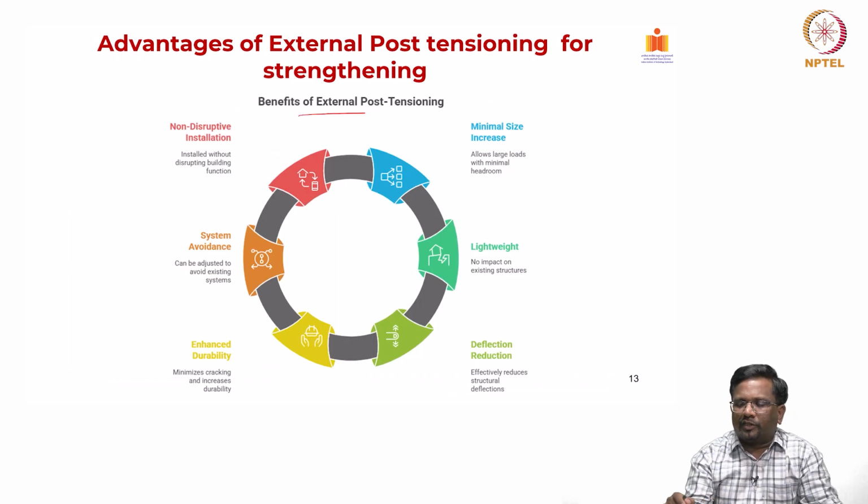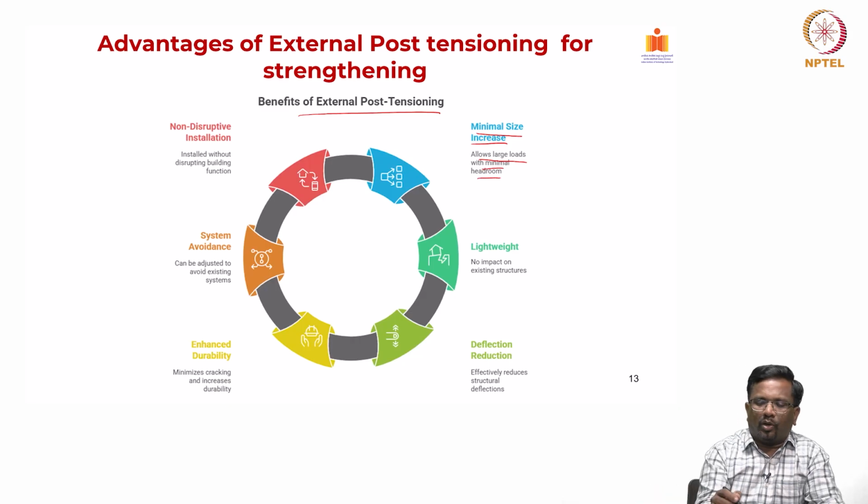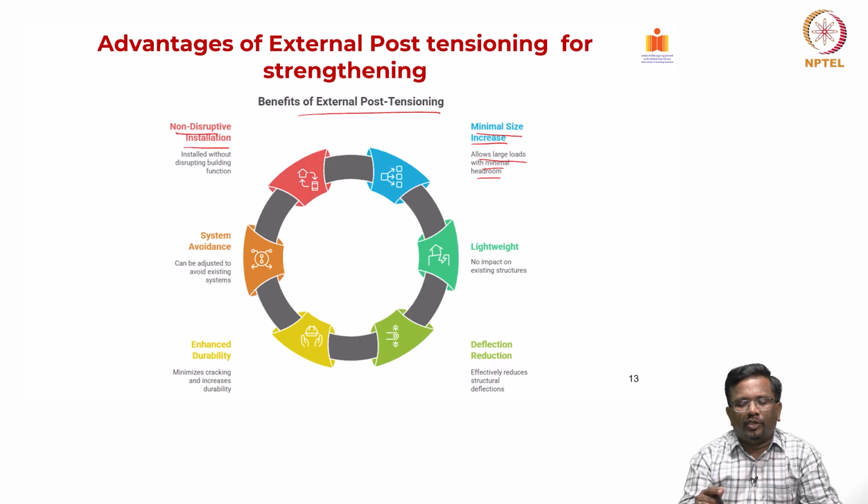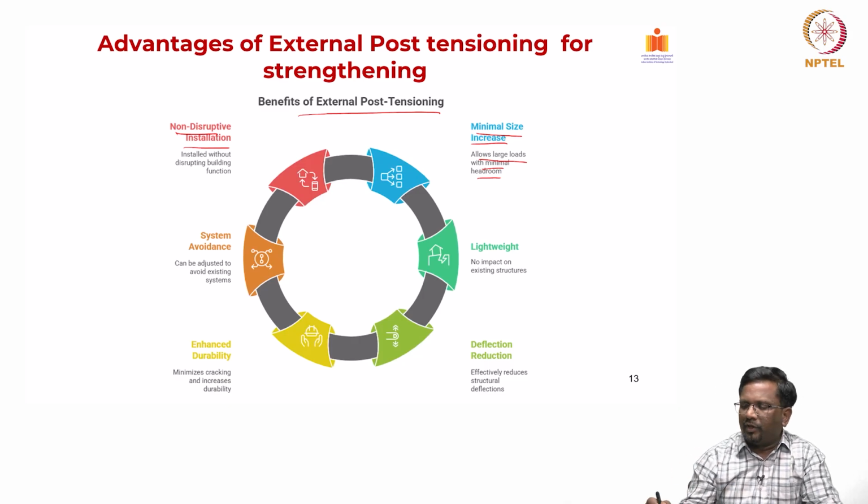What are the benefits of external post-tensioning? As you can see, it is basically not going to increase the size of your parent structural member too much. So, there is a minimal size increase. That means it allows for large loads with minimal headroom and non-disruptive installation. That means while the structure is in use, we can go ahead and do the installation without really disrupting the building function. Lightweight, and you are not adding any extra concrete.